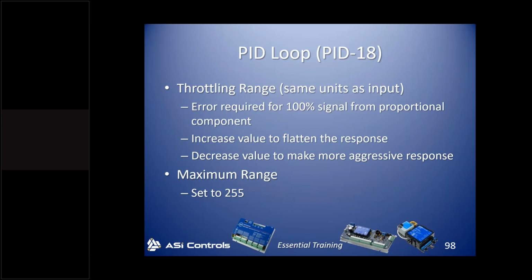And at some point, you see it switch from being too aggressive to too sluggish, or too sluggish to too aggressive. Then you've established that you can narrow down within that range, and then you can tweak it a little bit further. We can't go to that degree here in a simulation, but those notes you might find helpful when you're connected to a live system. So I just put in 100 to start.